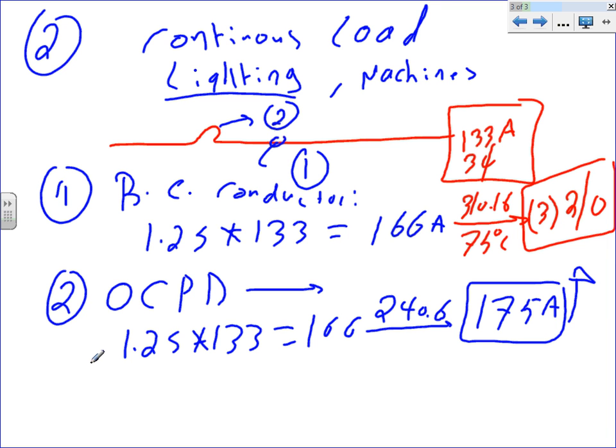One conduit, one feeder? Absolutely. Guys, when you go in the commercial building, you're going to talk about grouping. When would it be a good idea to group branch circuits and feeders? When is it a good idea and when is it not? It's definitely a very bad idea to group anything higher than 100 amp. Anything higher than 100 amp, bad idea.